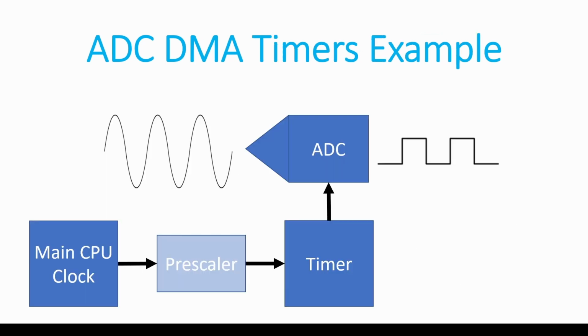While DMA continuous requests offered a sizable improvement in sampling speed, it comes with the drawback that the exact sample rate cannot be specified. Therefore, the third and final example will demonstrate how we can use timers to drive the ADC at precise sampling speeds. Specifically, we can configure a timer to generate a trigger event each time the counting period has elapsed. This trigger can then be fed into the ADC to start a conversion.